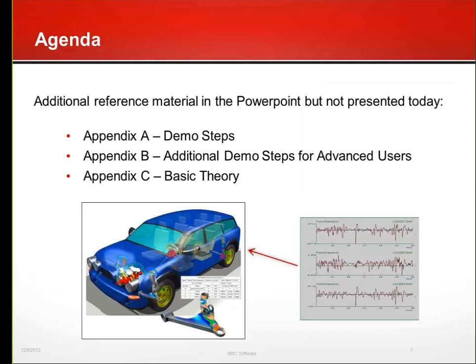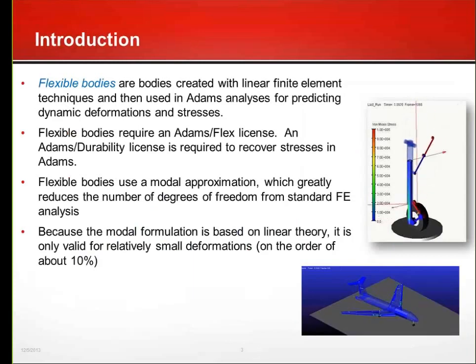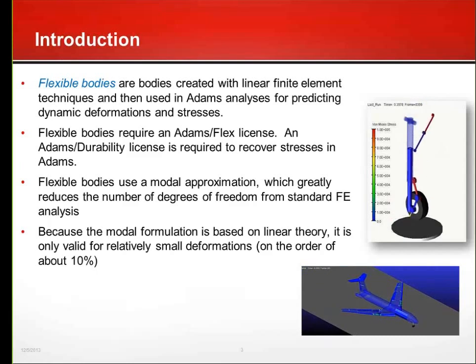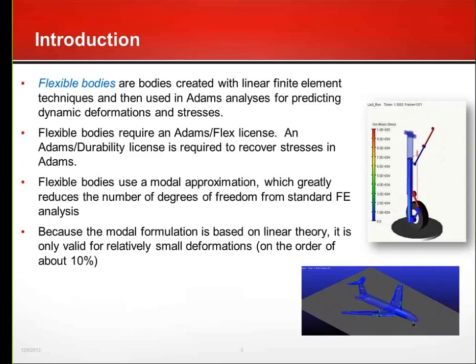Okay? So first of all, what is a flexible body? Well, for people who haven't done this before, a flex body is a type of part representation that's created with linear finite element techniques, and then that flexible part is brought into Adams for incorporating into a dynamic analysis, so that you can actually calculate time-varying deformation and stress within an Adams simulation.